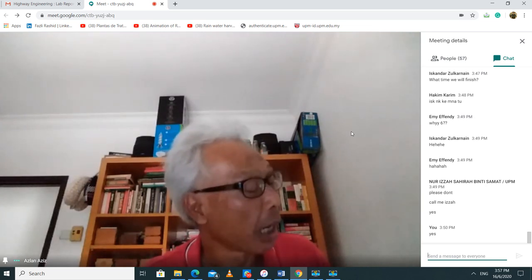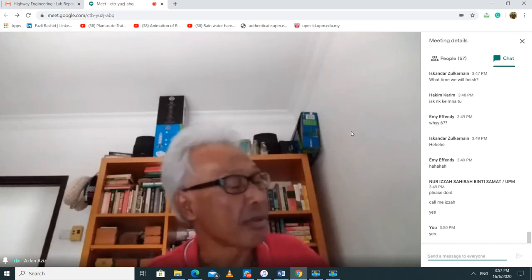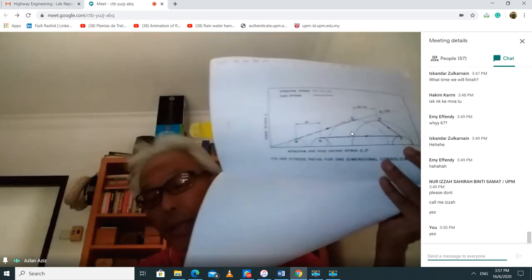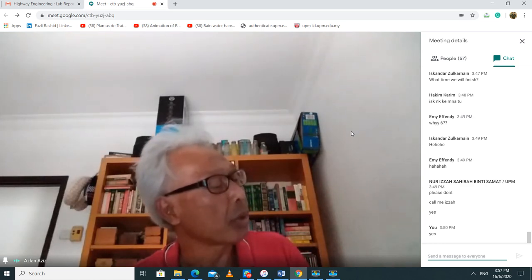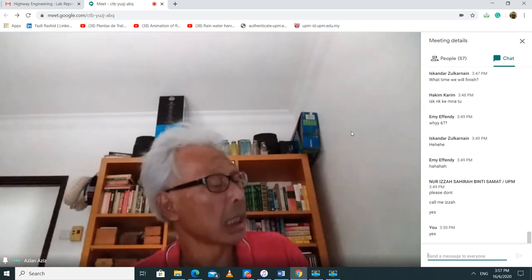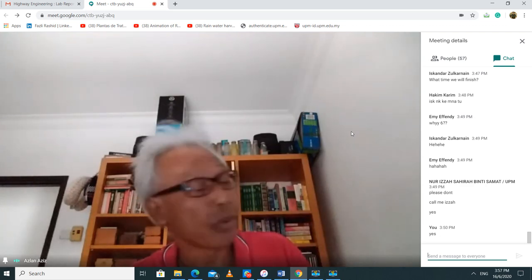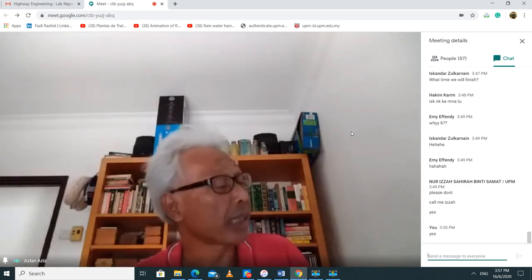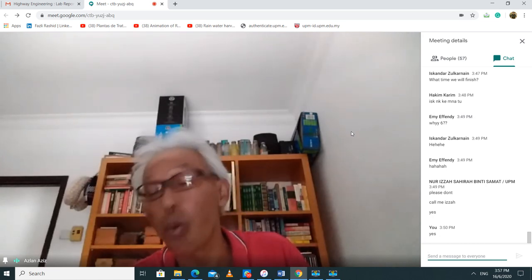So if you don't have figure 14.6, perhaps you can quickly look at it. I have figure 14.6 here. You see that they are different from figure 14.7. NPR is the total stress path for the one-dimensional consolidation, and then MQ is the effective stress path, which follows the K sub naught line in the one-dimensional consolidation. So that effective stress path MQ is not the same as MOQ.